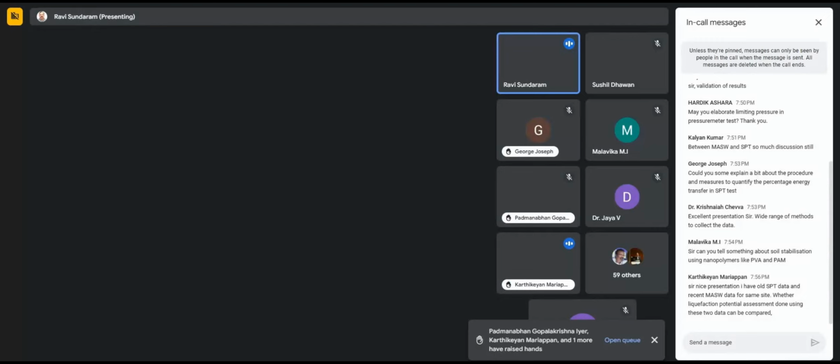Most of the literature is saying that liquefaction potential assessment has to be done at ground level only. They are saying, whatever is the worst condition you feel, the highest groundwater you expect during the life of the structure. So as an engineer, you have to estimate how much would be the highest.